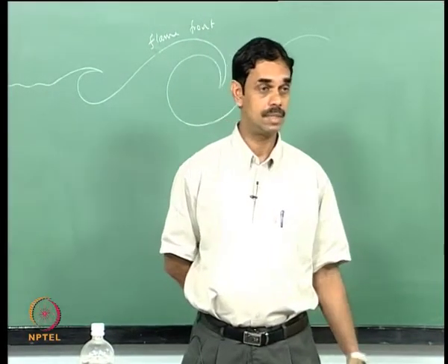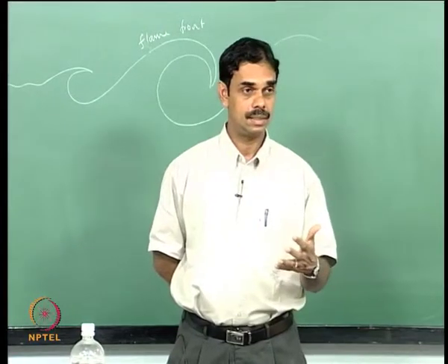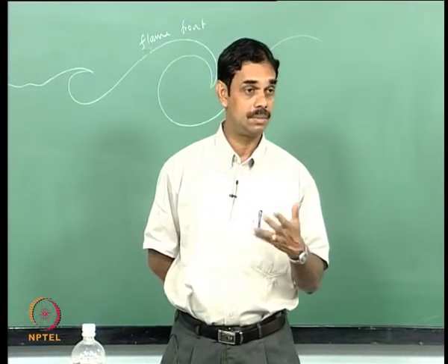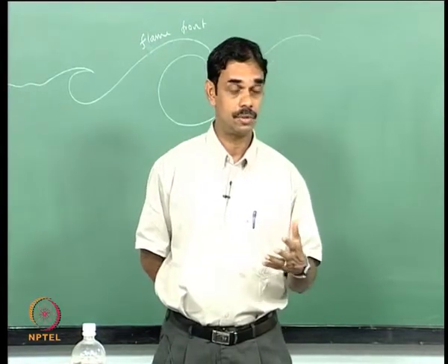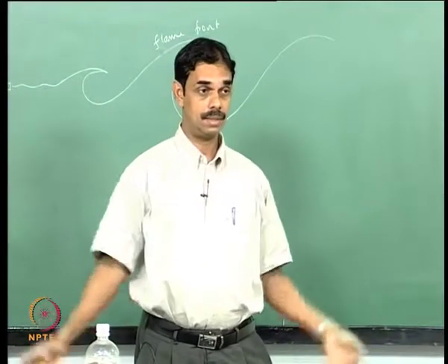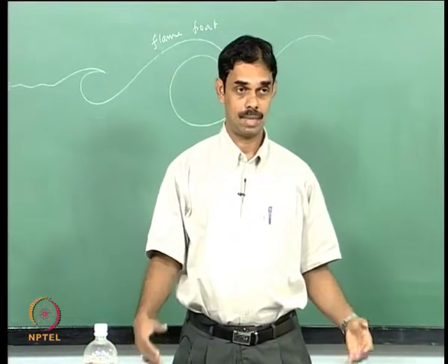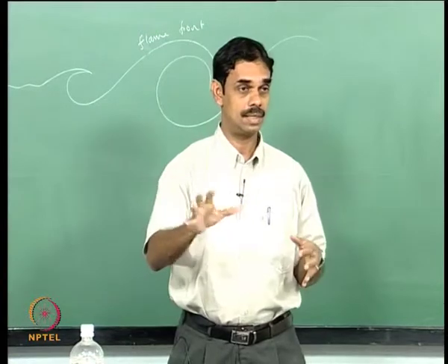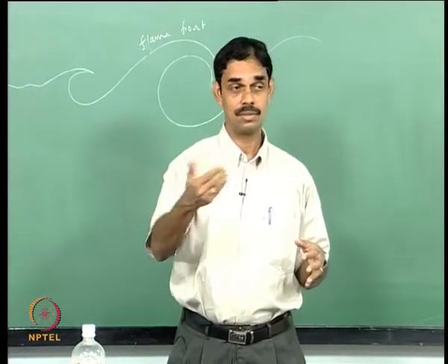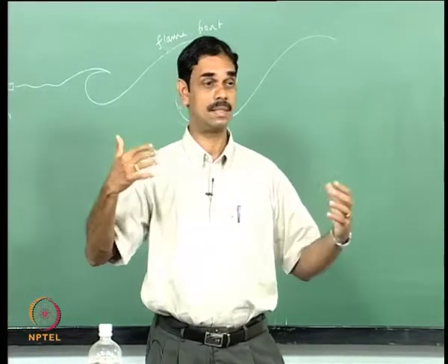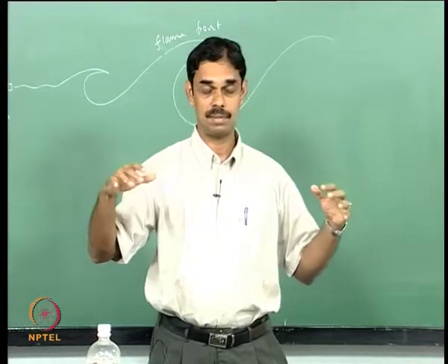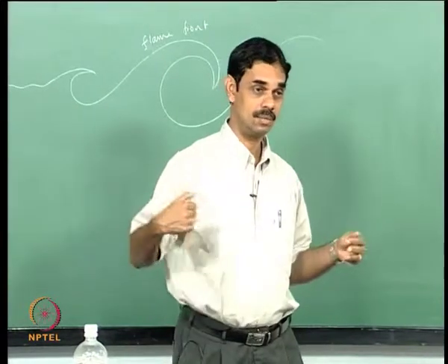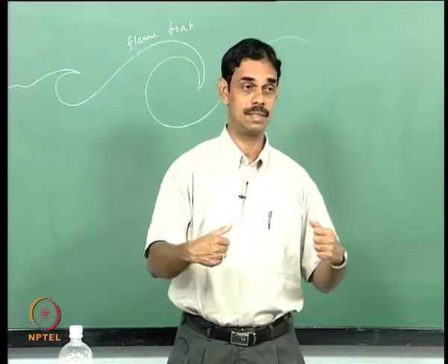Another possibility is you can change what is being injected, the distribution of injection. If you are talking about an annular combustor, you can have each injector with a different injection velocity, so that you have a time delay, but each injector has a different time delay. So it's like a distributed time delay, where everything is not coming bang at one shot, but instead one comes first, another comes next, another comes next.